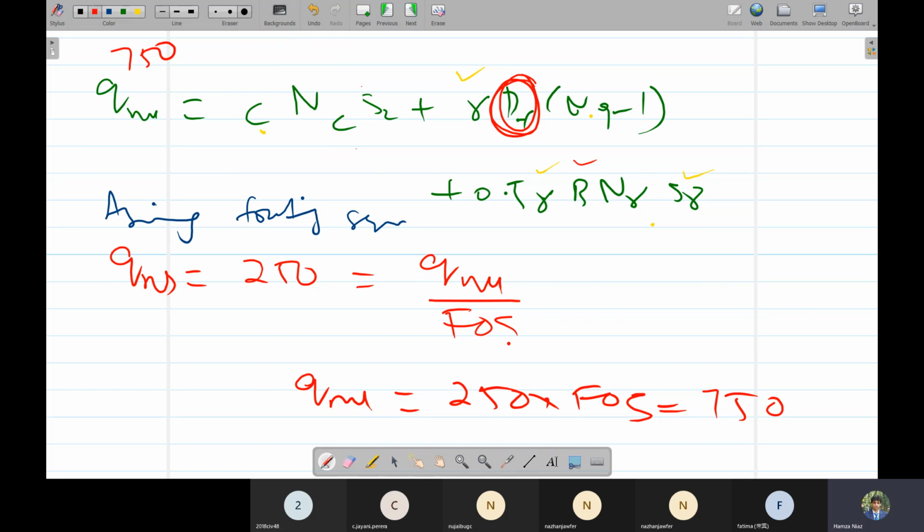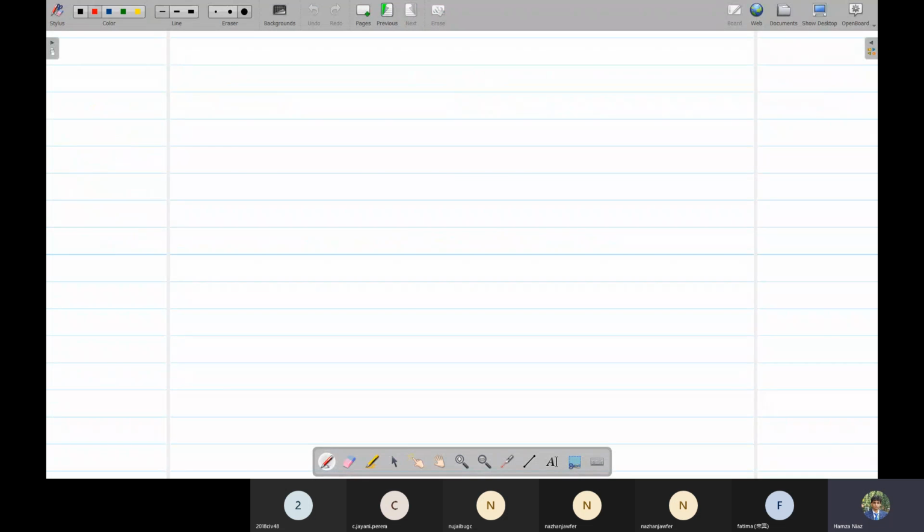So we have to find the width of footing. So here this one would be unknown. So our net ultimate value would not be a single value, but it would be something like an expression. But q net ultimate would be something like 50,000 plus 1000 B.